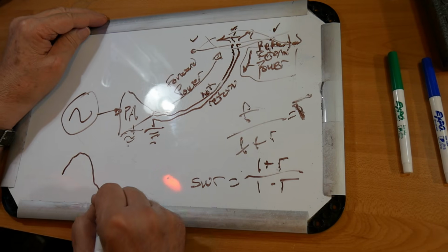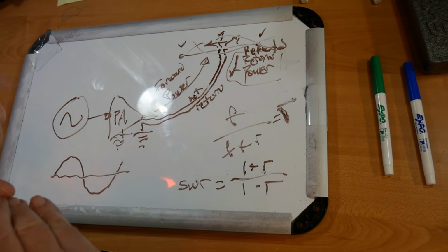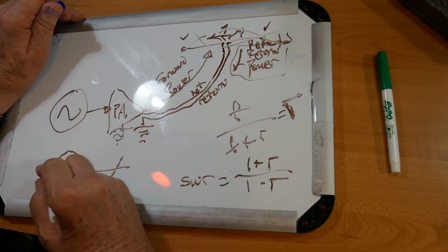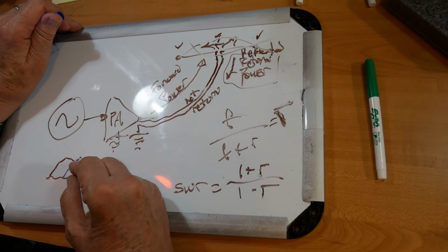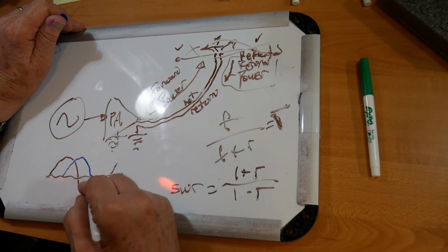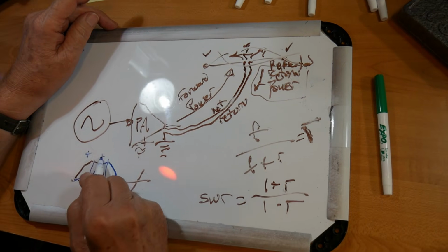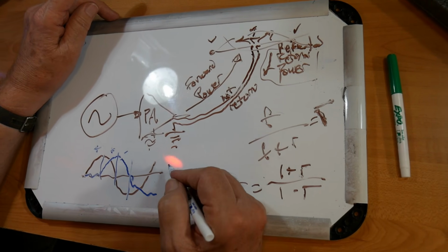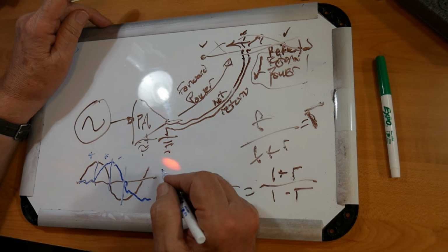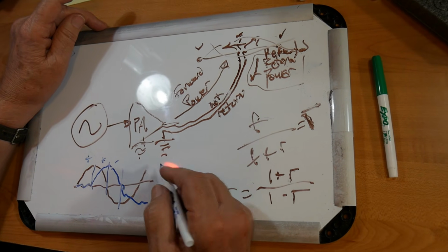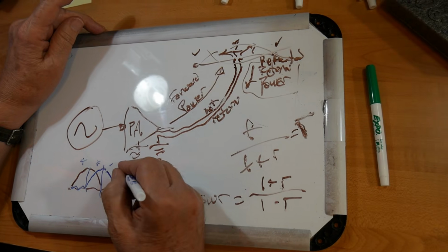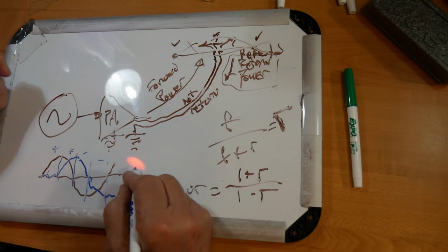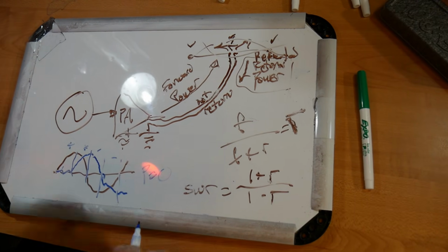If we take a wave like this, and we have another wave that is 90 degrees out of phase. So this is the voltage. Here is the current. Okay. So that's positive power. This is positive power. Now note here, this is positive while this is negative. So that's negative. Okay. So where do we come up with our other negative? And here it is negative. So we have positive, positive, negative, negative. And the amounts are equal. So the power, the total power, is 0.